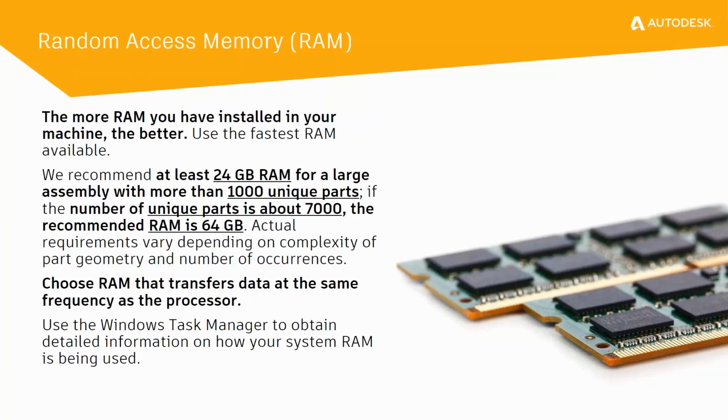So keep that in mind if you are encountering issues running out of memory and potentially having to use your page file or virtual memory. Increasing the RAM that's available for Inventor to utilize when working with large assemblies can significantly improve performance.